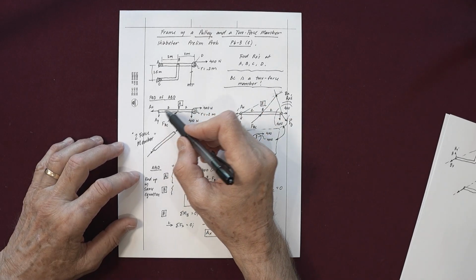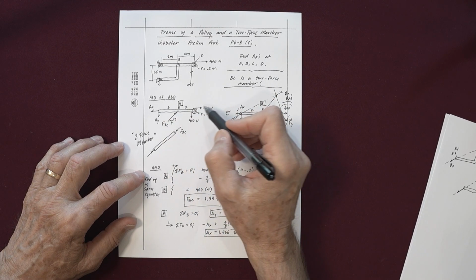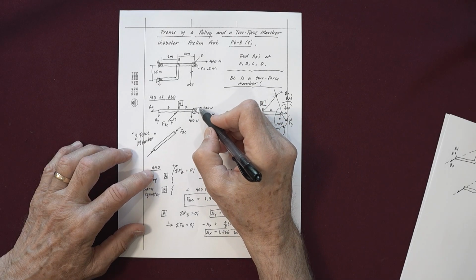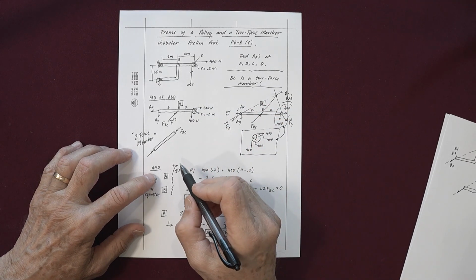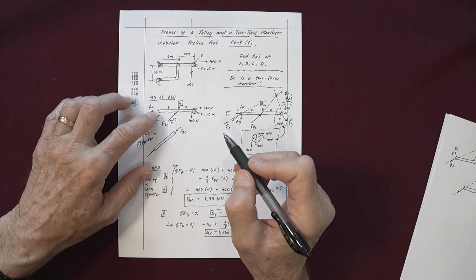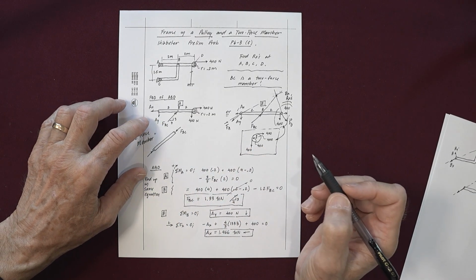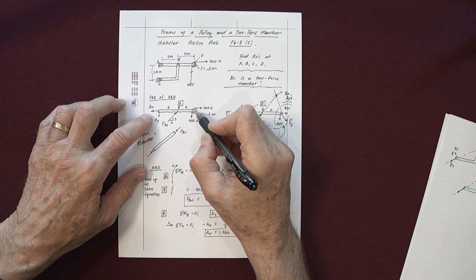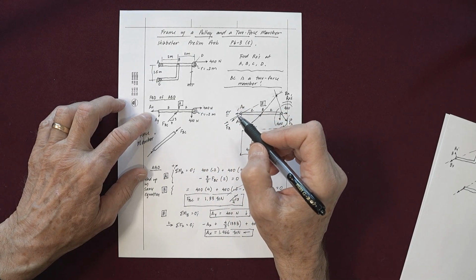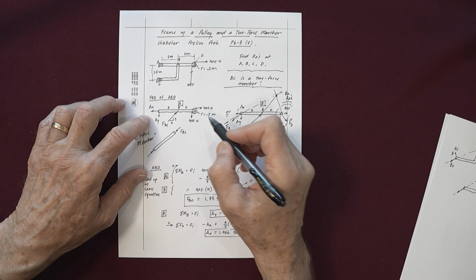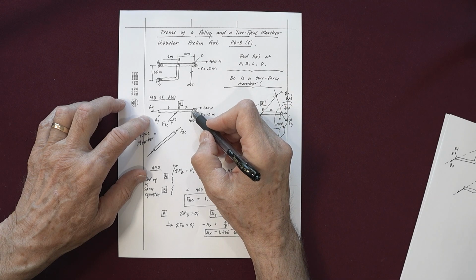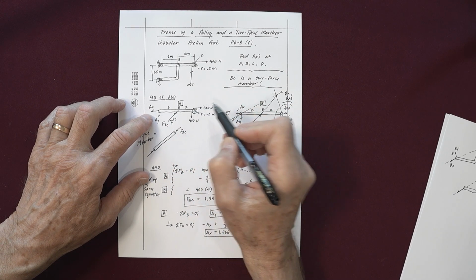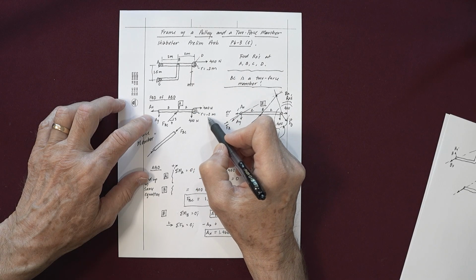So let's write the equations for ABD. If we leave the forces on the pulley, if we sum moments about A, and we take clockwise to be positive, we have this 400 times 0.2 positive, plus this 400, and so it's 4 meters all the way to the pin, and it's minus 0.2, the radius of this pin.